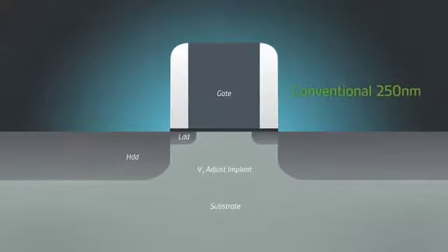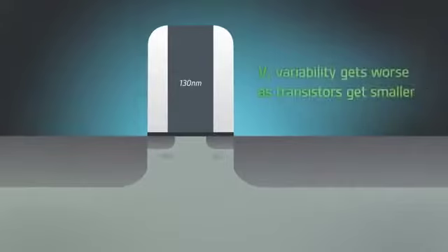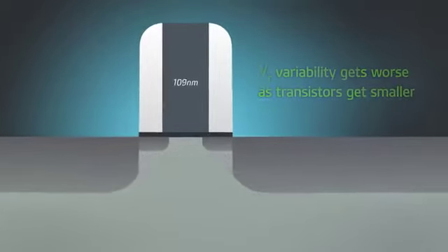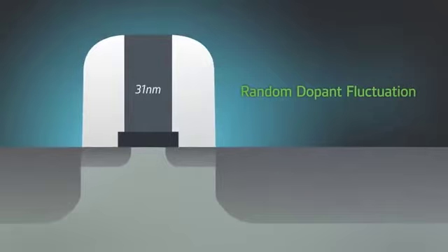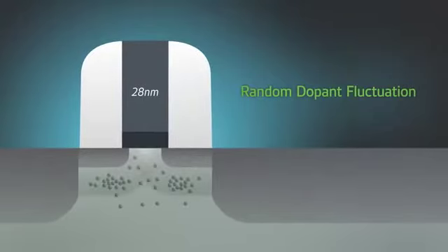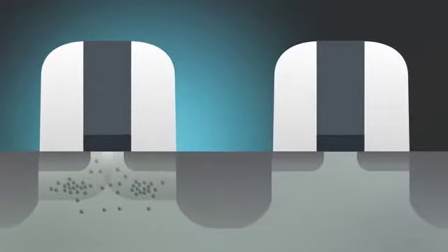voltage. Looking at a conventional transistor, the primary reason voltage doesn't scale is variability in threshold voltage, or VT, which gets worse as transistors get smaller. A primary cause is random dopant fluctuation in the transistor channel. Even with small differences in channel doping, threshold voltages can vary dramatically from one transistor to another. With billions of transistors on a chip, VT variability becomes a big problem.